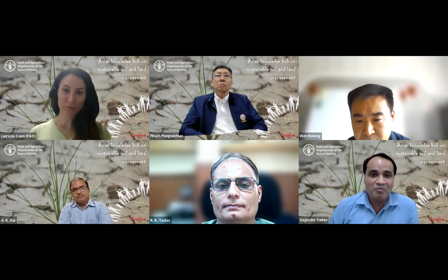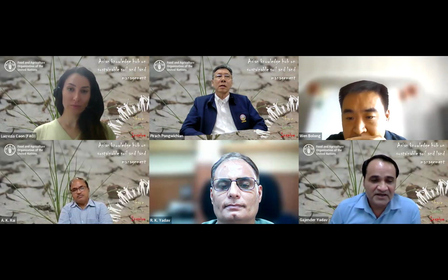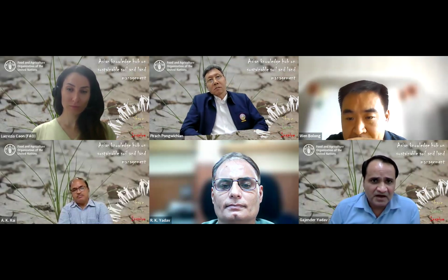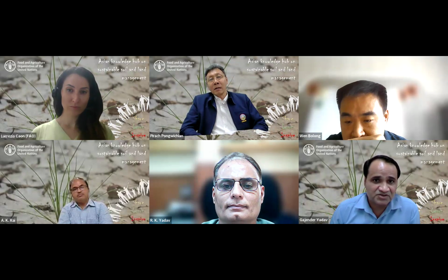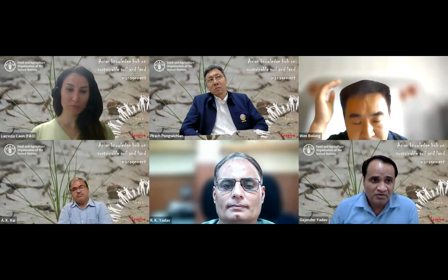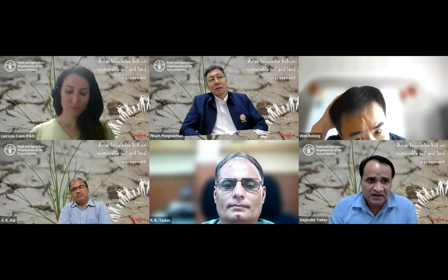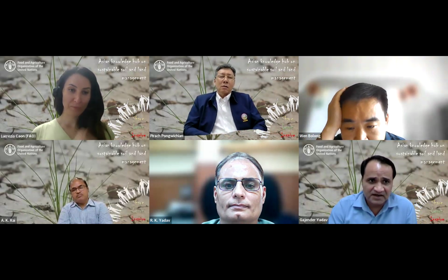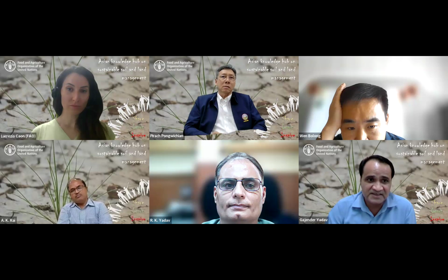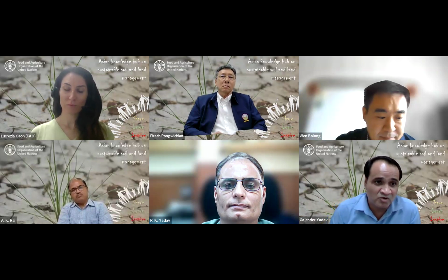Yes, the optimum depth in lighter soil is 60 centimeter, you can say. But in heavier textured soil, if you are not able to pull the machine because of the hardness of the soil, just make it a bit shallow. The one wheel that is visible on the machine is the depth control wheel. So as per your requirement, for proper drainage function it is around 60 centimeter, but you can go 35 to 40 centimeter as well. In heavier texture, shallower, and in lighter soil, up to 60 centimeter or more is suitable.